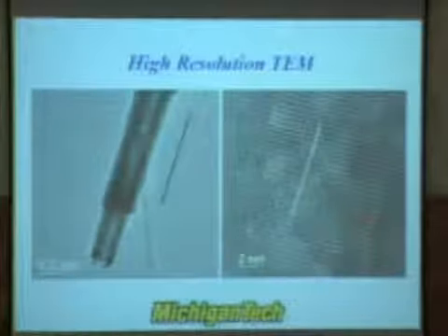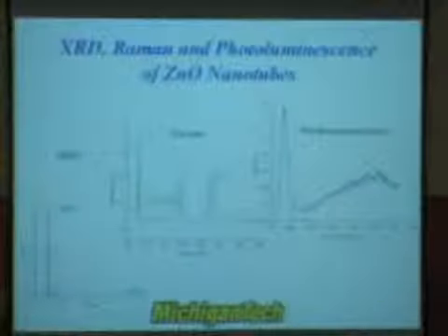And these are single crystalline structures, just some details of the properties. So let me quickly summarize zinc oxide. Uniform band gap, you don't have to sort them, right? Multifunctional. You can make a vertical transistor. And the challenge will be large-scale synthesis and operation and the performance. Doping is still an issue, although p-type has just been reported last month.